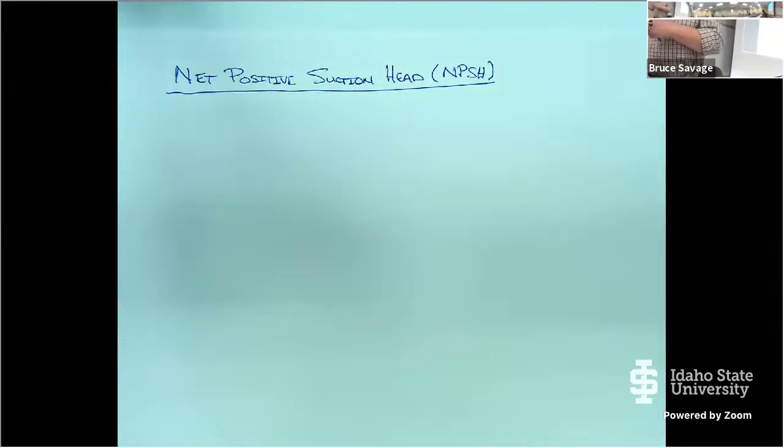And when they do that, they move the water away very rapidly. It's like a tow rope is coming along, and you're off to the side, and all of a sudden you decide you want to grab hold of that tow rope. It's going to jerk you forward, and if you have a friend standing next to you, they're left there, right? So the blades grab the fluid and move it, and the fluid right next to you is still there. They may fill your gap because the blades create a suction. But if it's too big of a suction, then we get cavitation.